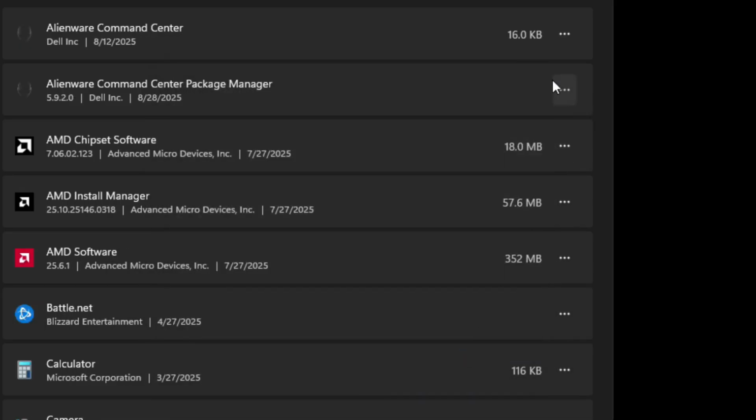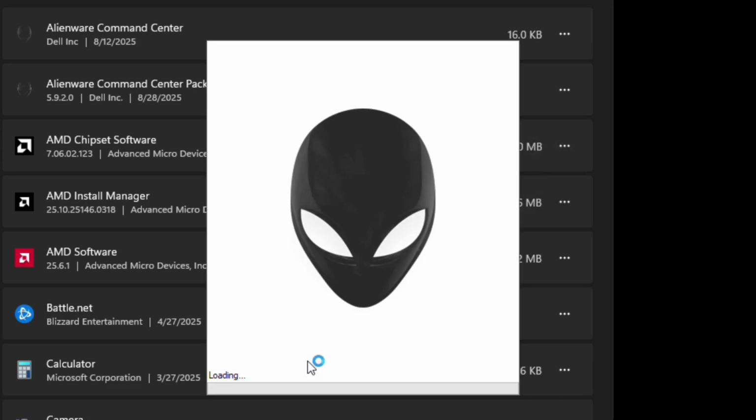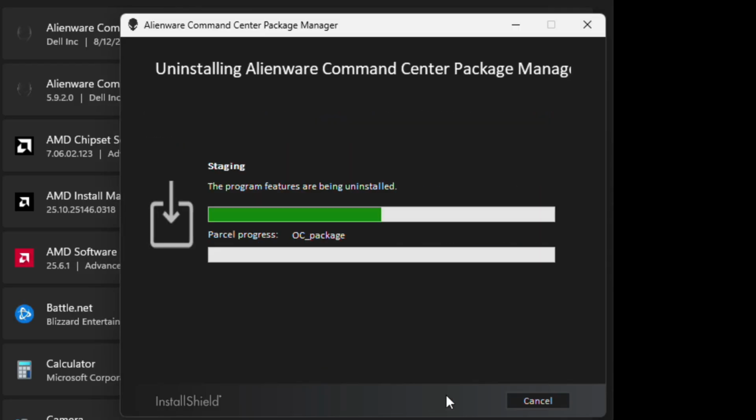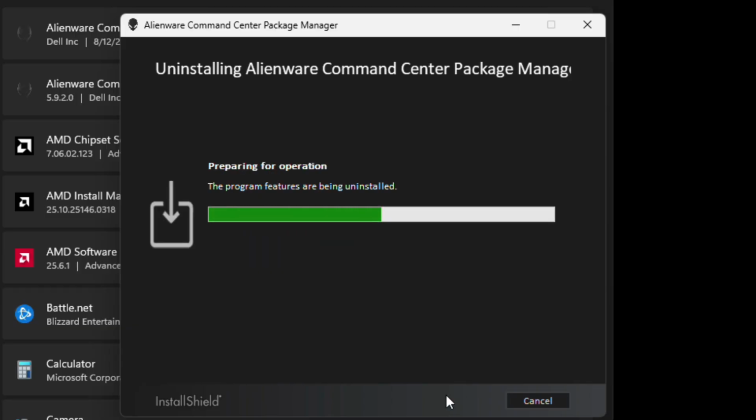If you have a different keyboard, you can take this framework and modify the HID reports for setting the colors to the protocol used by your keyboard. In general, most keyboards that I've seen work in a similar manner where it has a number of initialization packets that are sent, followed by a sequence of packets that have the individual RGB settings for each key in them.